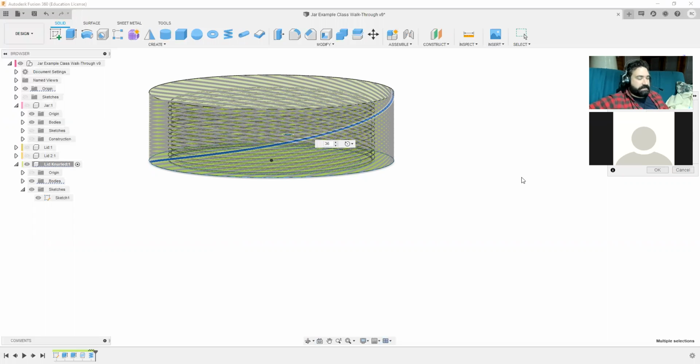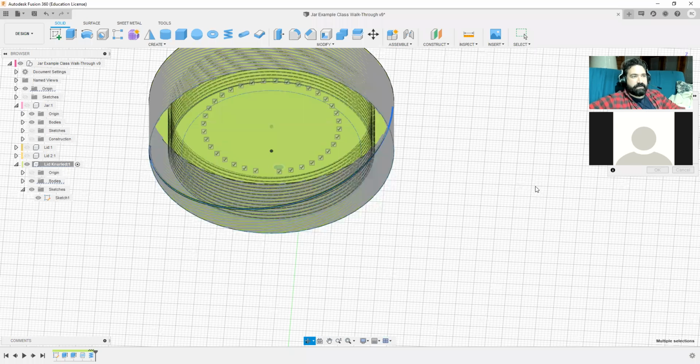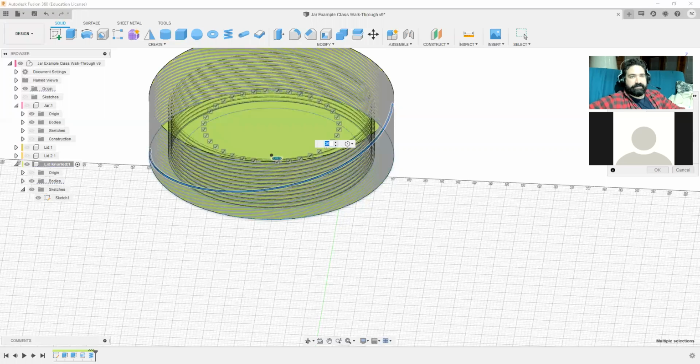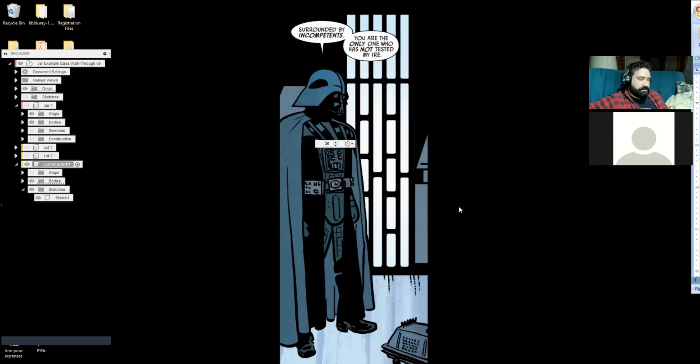Yeah, I don't need to deselect anything, so I'll uncheck suppress. Suppress this checkbox here is if you wanted to omit any one in particular, or any few in particular. So if you wanted to make an irregular pattern with this, your items could still go the full 360 degrees. There's 36, so there's one per degree. But say you wanted a couple of whatever you're repeating to be omitted, that's what that would do. So click OK, and it's going to start computing. And hopefully not crash. Yay!